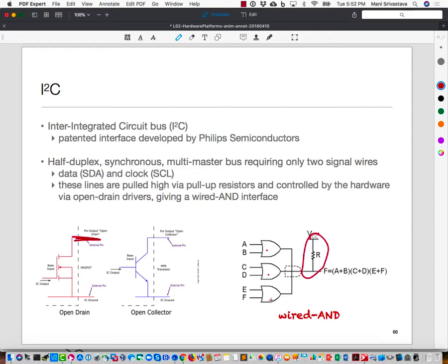Okay. So going back out here, the transistor is off, so the current cannot flow through. So it's as if these 3 guys are disconnected from the wire, right? So what will happen to the voltage? It's called a VCC, right? Because all that's happening is it's just being pulled up, right?